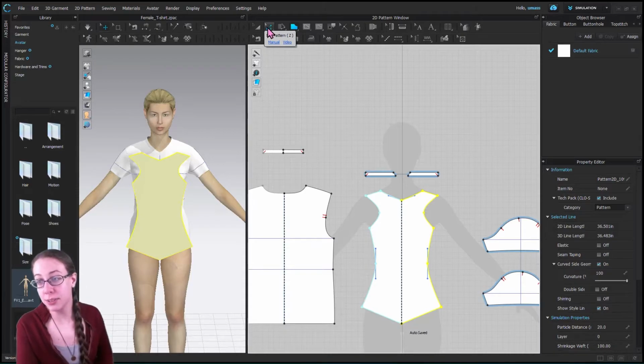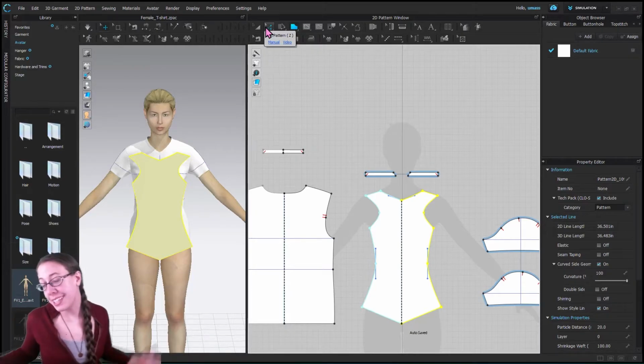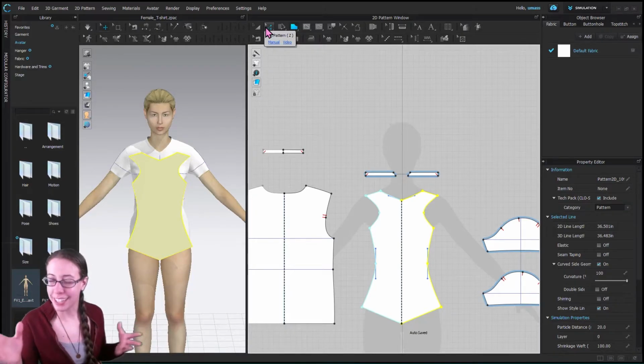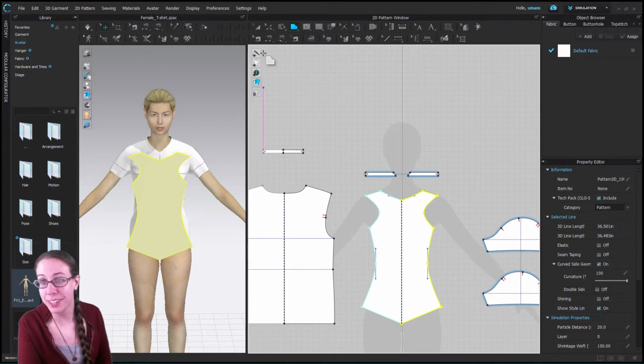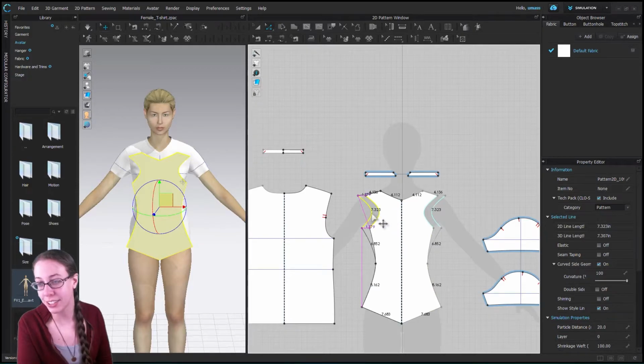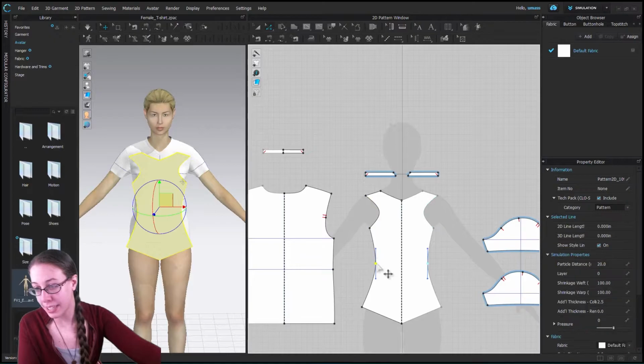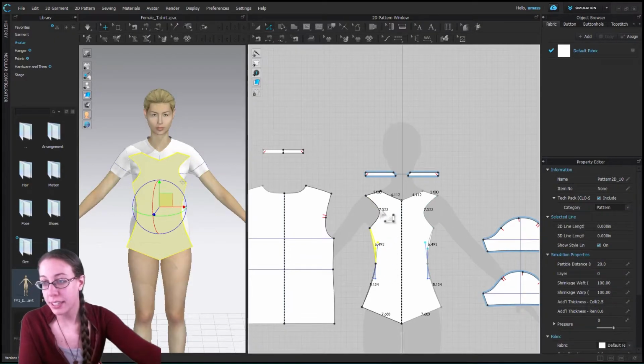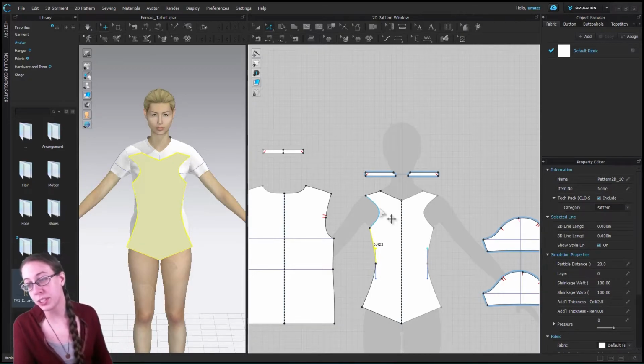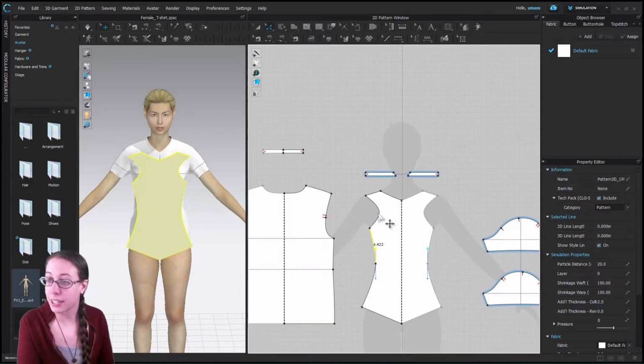The edit pattern tool can only be used on Bezier curves or Bezier points. So when we click edit pattern, we will actually lose sight of the curve points that are here, and we won't be able to edit this curve the same way we can edit a Bezier curve by adjusting the handles and everything. The curve point curves will not look like that.